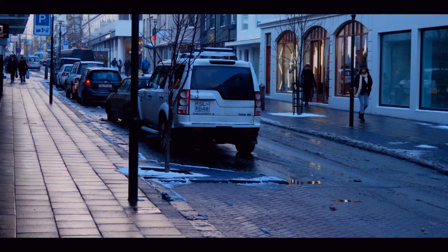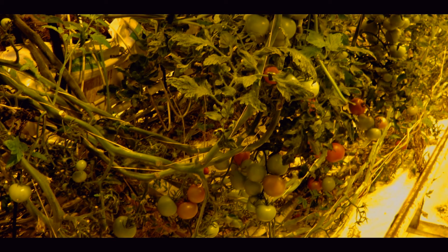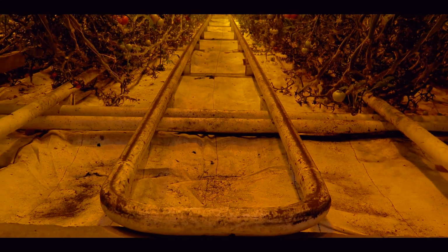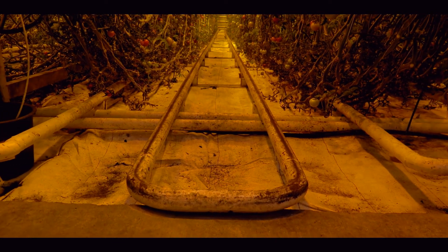They also put it in on the streets, and here you can see a sidewalk. They have a circulating loop, and with that, they don't have to shovel snow when it snows. So great application of natural convection in Reykjavik, Iceland. There we can see three different applications: electronic cooling, household heating, as well as growing tomatoes in Reykjavik, where they were using the heat and the tubes in the bottom of the greenhouse in order to provide the heat for the growth of the tomatoes using natural convection.